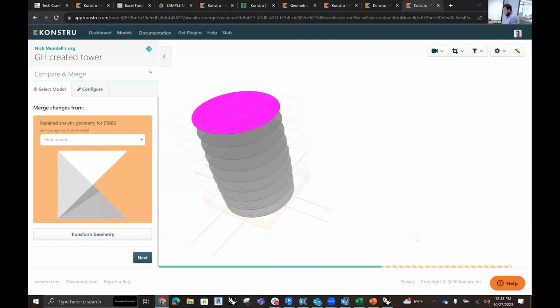So, question: does the RAM model merging to Revit need Excel edits? Technically, yes, simply because it's raw data from the RAM model being sent to Revit. Now, it's possible for things like number of studs and camber, you don't need to do much factoring or rounding to those values, because RAM usually does a pretty good job of hitting the studs you want.